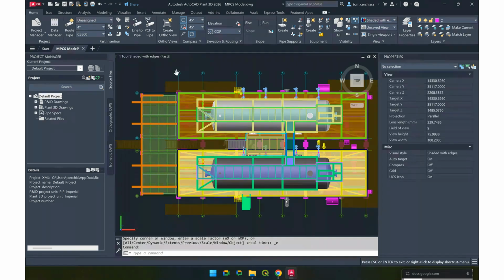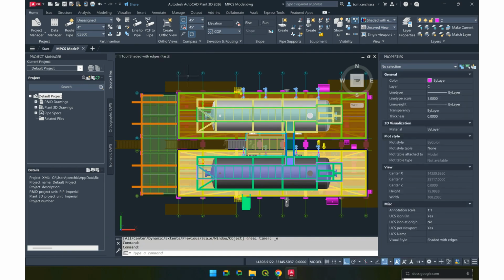Okay, let's measure that again. There, right there, 10 feet, much more reasonable. Okay, so we have a clean drawing. We have a drawing where the units are set appropriately, and we have a model that is scaled to the proper scale here, where 1 unit equals 1 foot. Now we can worry about georeferencing that, and then we're going to step over to PIX4Dcloud for the first step in that.